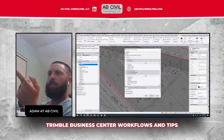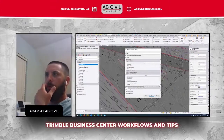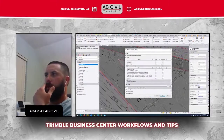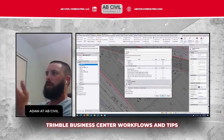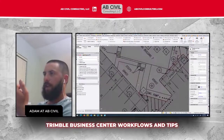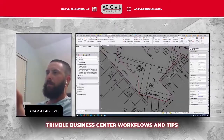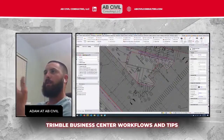If you go into your advanced view filter menu right here, and you scroll down, georeferenced image. Right now they're checked. Some of these are checked selectable because I just brought them in separately. I always turn that off because when you're clicking on a line, if I want to click on this line, if that PDF is selectable, when I click, I'm going to have two options: the georeferenced PDF or the line. And for all the work that I do, there's always a PDF behind it, so I always turn that off.